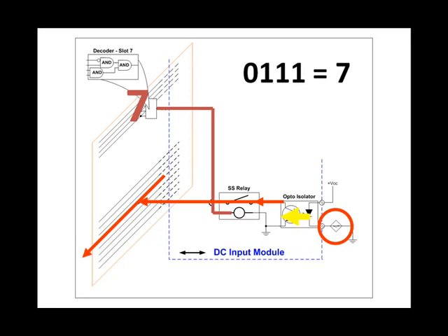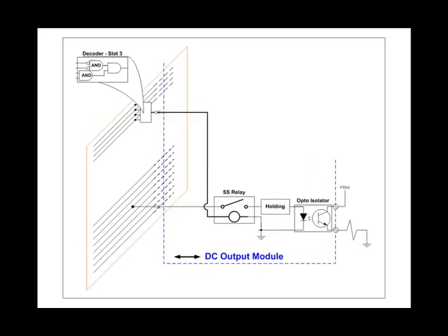The controller is sending something to the output. The processor writes the state of these outputs across the backplane to all of the modules. When the slot is activated by its decoder, and even though the 16 outputs are all felt at all slots on the backplane, only one slot is activated.